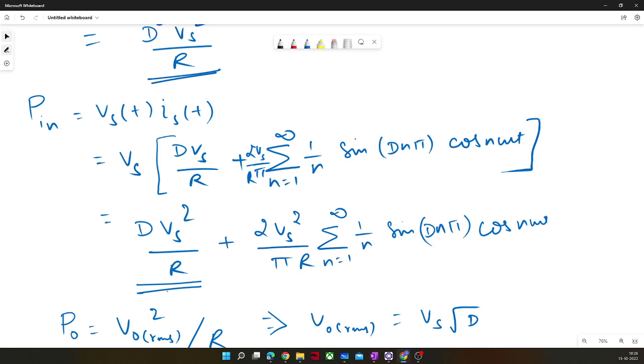And if someone asks you that there is no loss from AC to DC, you now know that there would be some loss in the harmonic component. So you can state that. Generally, at UG level, we consider it as ideal, but nobody knows when someone would ask anything. So it is better to just keep it in mind. However, we will use this expression very extensively in the inverter, because in the inverter there are so many waveforms. So we will deal with these expressions.